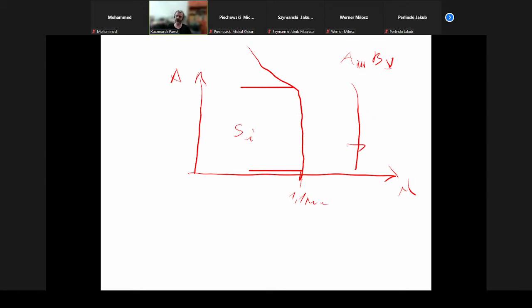In fact, they are inversely proportional to each other. So above this wavelength, they start to be transparent. This is why, for example, the silicon detector cannot be used for the second and third telecommunication windows, because silicon is transparent for this wavelength, so the light cannot be absorbed. It cannot create the electron-hole pairs needed to create the current driving our photodetector.